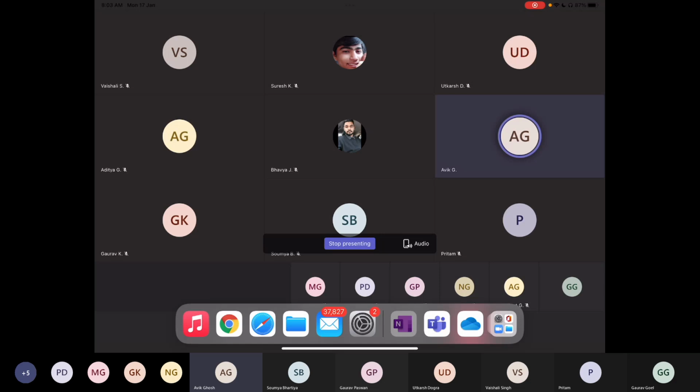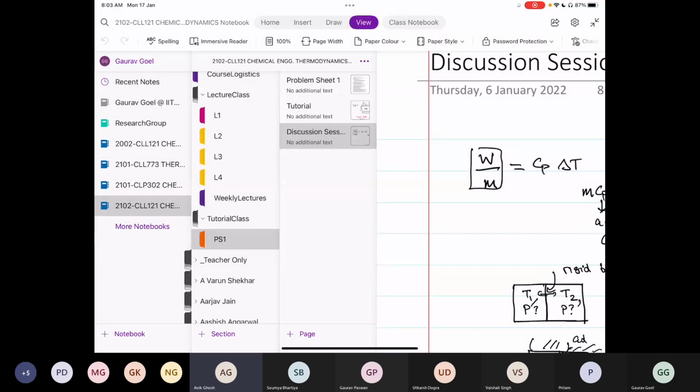So I have a question from lecture 4. In the energy balance equation, you have said that for laminar flow, the average kinetic energy is U square, and for turbulent, it's half U square. But for laminar flow, if I calculate the kinetic energy, it turns out to be like V max square divided by 6. If I integrate, so how U square there?